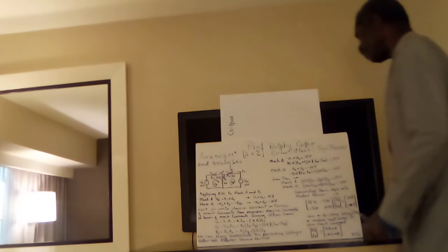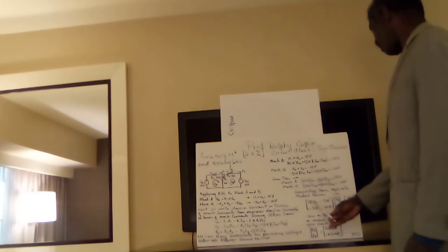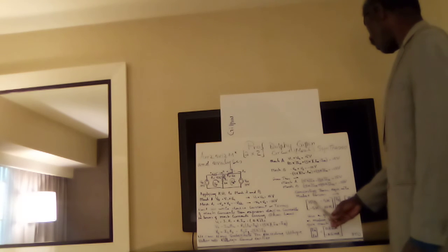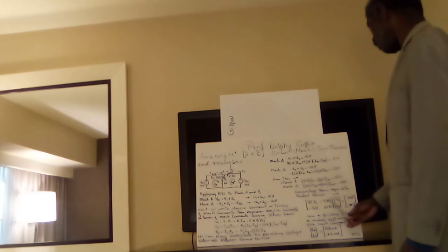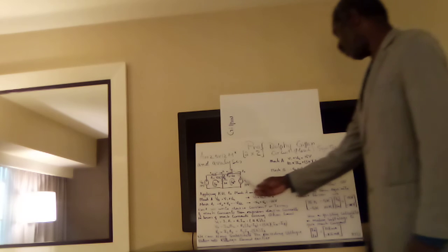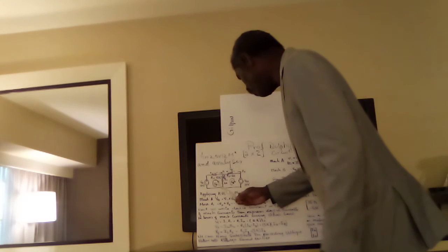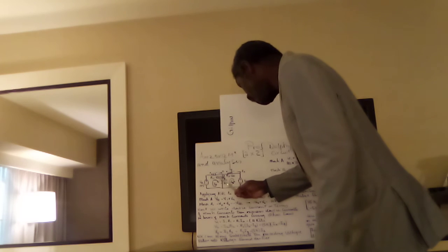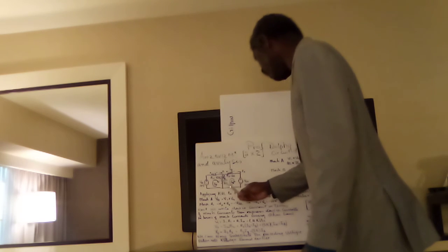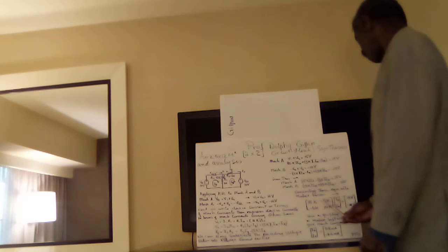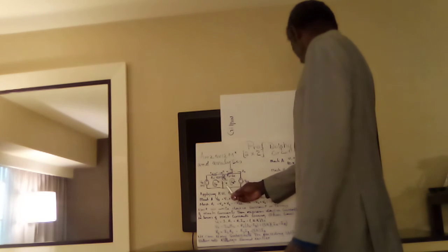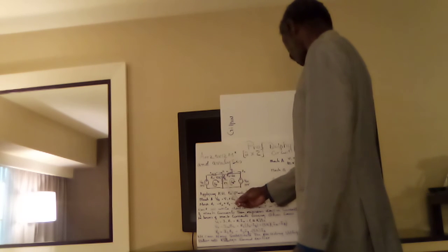And now we convert this equation into the matrix form. And we get that this is R11, this is R12, and we use it from here. R11 is equal to 15K, which is 10K here and 5K there. And R12 is equal to minus 5K, the resistance common to 1 and 2, which is 5K.